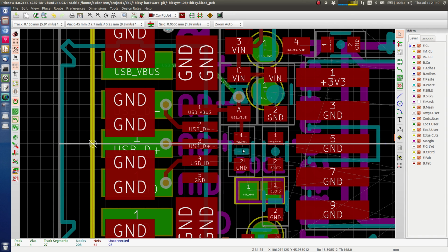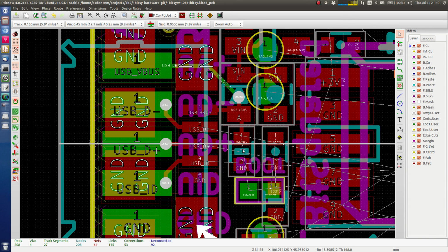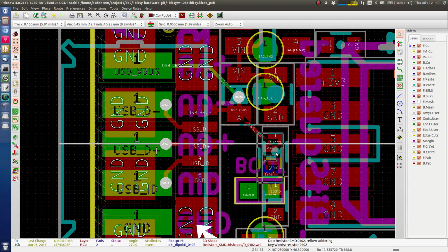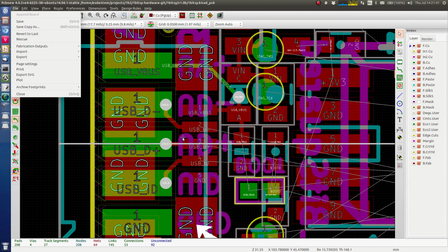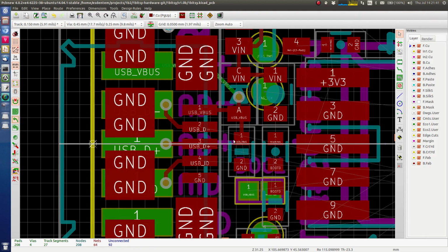But is it in the classic mode, or is it like so in F9 mode? So grab. Yes. There you go. So that's the difference. It works in the legacy mode. It does not work in the OpenGL mode, which is what I'm using all the time. It's actually the F11 OpenGL mode. So you have to go into the legacy mode to keep the stuff attached.